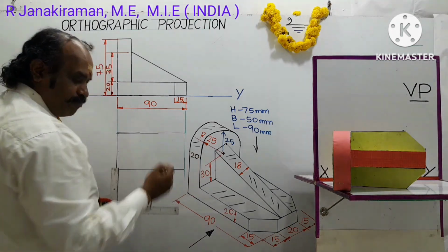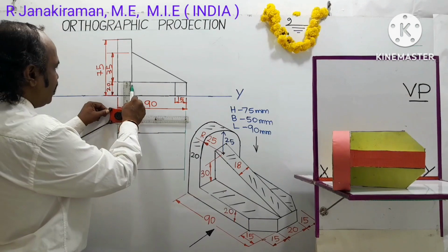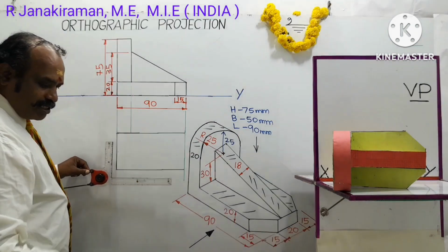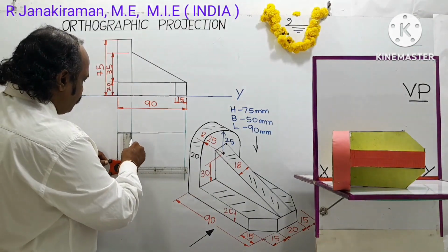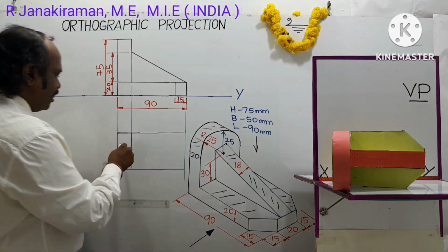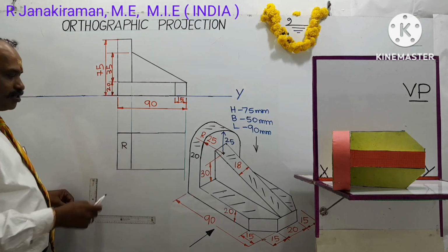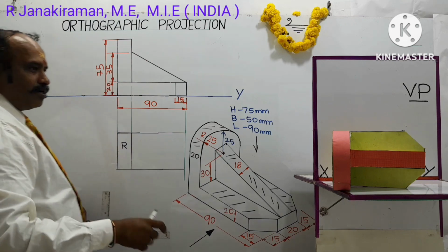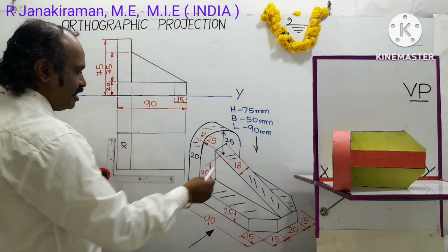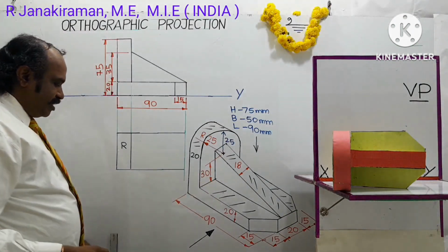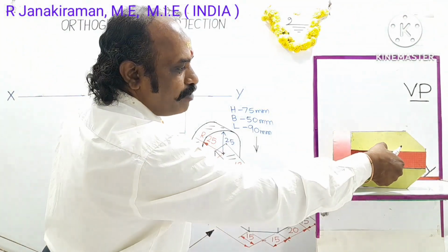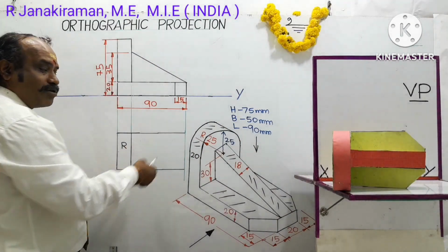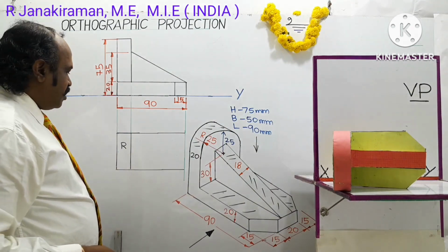Okay. So from the previous front view, draw a vertical projector where it intersects with this rectangular box. There you draw a continuous line using HB pencil. This forms the red color portion. The red color portion will have the thickness of the red portion, and the breadth shall be seen in the top view. Okay, this is the top view. And at the center, this 18 mm is the thickness of the triangular part, passing through the middle of this rectangle. Okay, so we'll construct that.